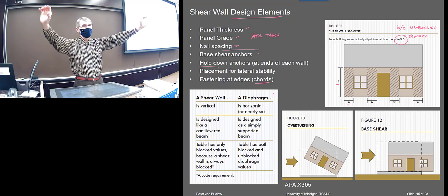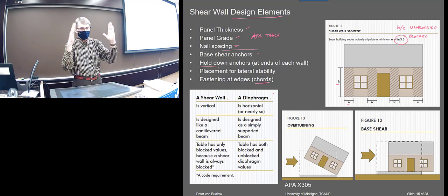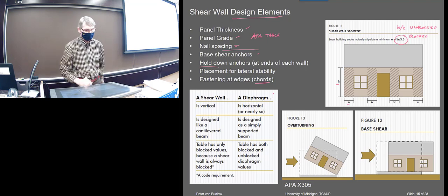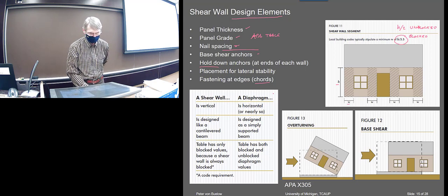Those collector struts have to be designed, and in a shear wall, I guess what we're talking about now, you have to design the strength. But usually, they're not that high if you have the full area in tension. And maybe they're doubled. It's a matter of whether it's a single or a double, but they're almost always doubled at the corners anyway. So if you've got them doubled, they're probably going to be strong enough.